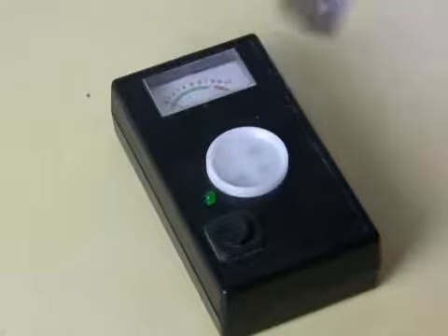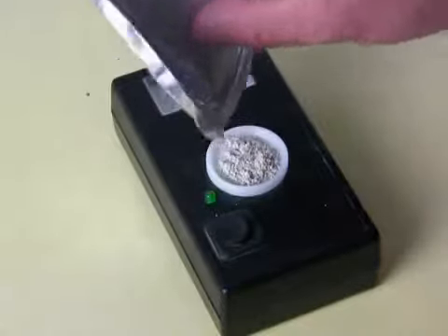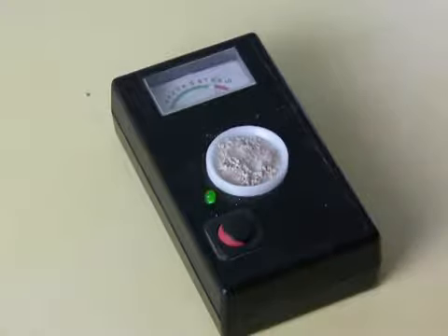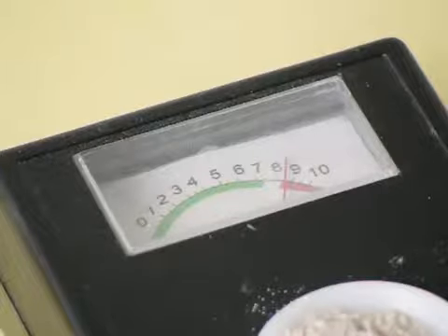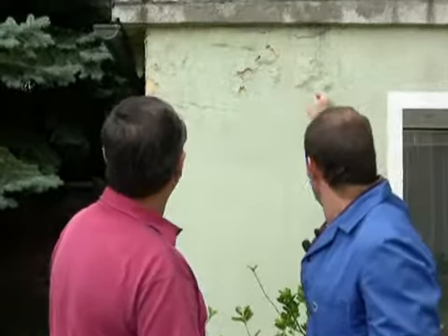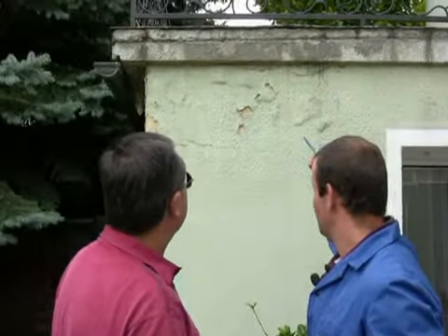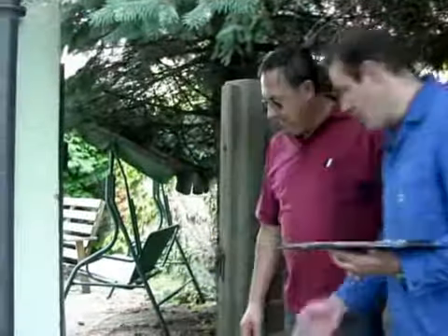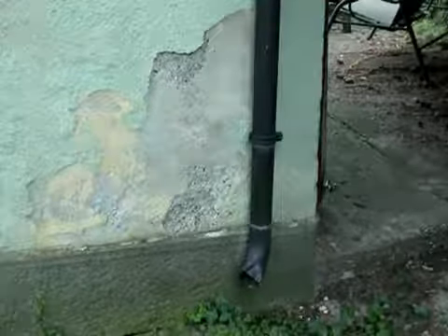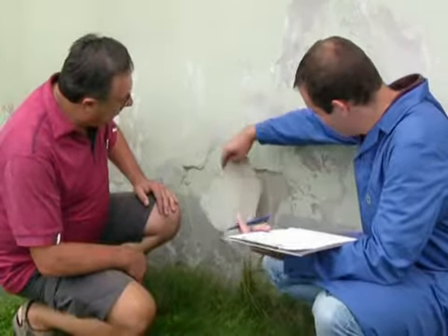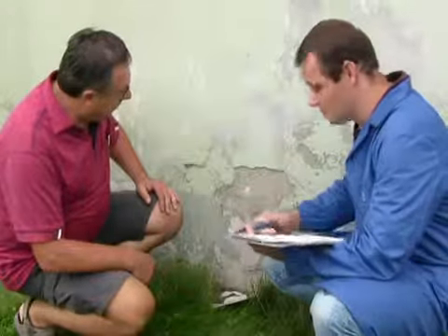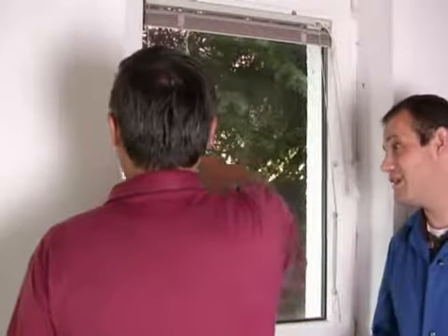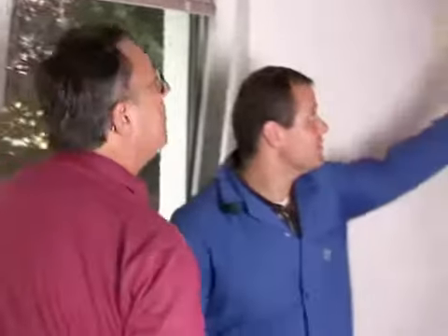Diagnostic investigations of masonry provide further information about the condition of walls. Any accompanying measures that may be required are then discussed with the client. Accompanying measures may be needed to prevent local hindrances to the drying out procedure. Such measures include the repair of the roof water runoff system, removal of moisture-blocking layers or layers containing excessive salt. We also discuss ventilation habits in order to reduce or prevent condensation water.